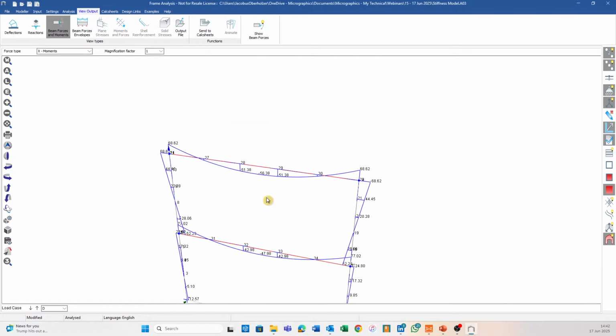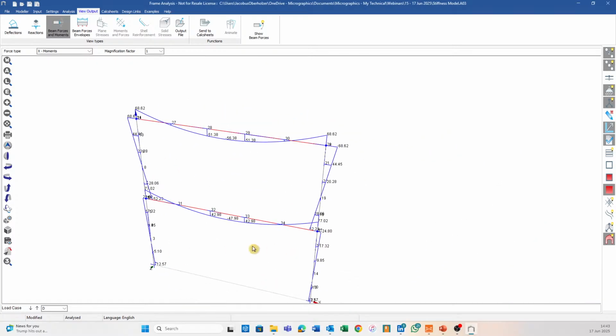Even if we just had to create a copy of this frame here and connect it in the Z direction, we already are entering into a space where it can become incredibly complicated and time consuming to actually calculate, to go to IDEA StatiCa, calculate all of those rotational stiffness values, come back, incorporate them, and assign them correctly.